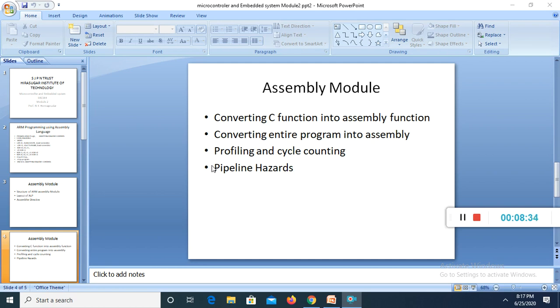Then in step 1, remove the C definitions, keeping only the declarations, and produce a new C file, main1.c. Then step 2, add an ARM assembler file, for example square.s, with the following contents: AREA, text, and read only. You can export values that you have to enter.